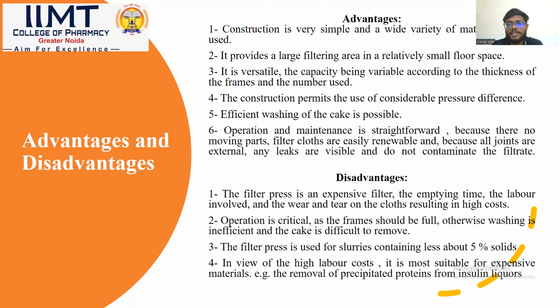Operation and maintenance are straightforward because there are no moving parts. Filter cloths are easily renewable, and because all joints are external, any leaks are visible and do not contaminate the filtrate.